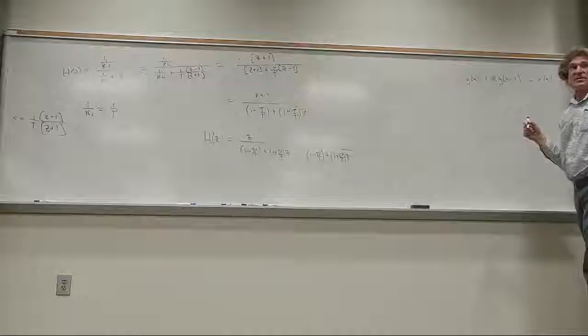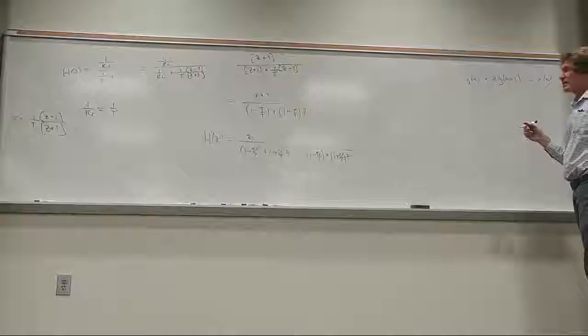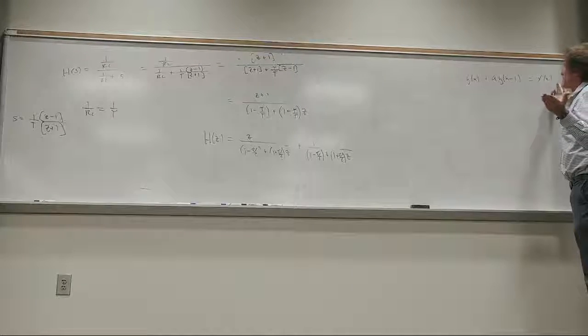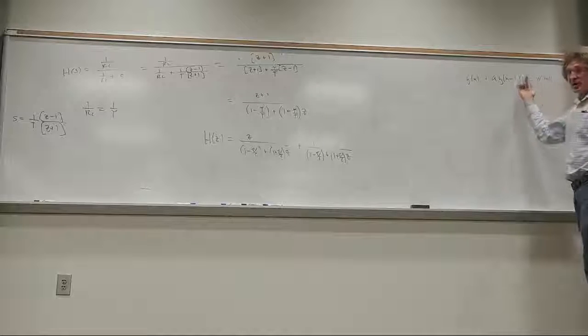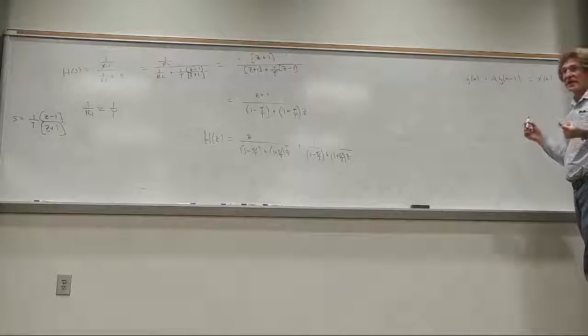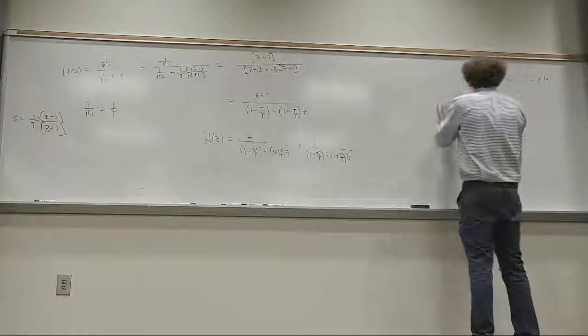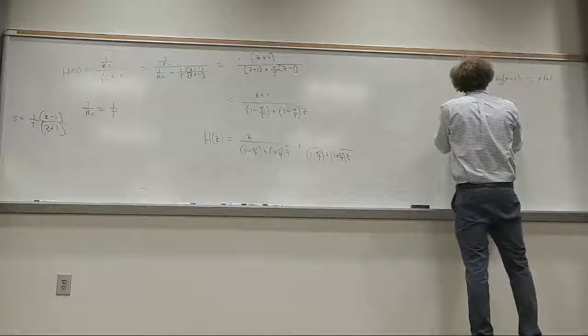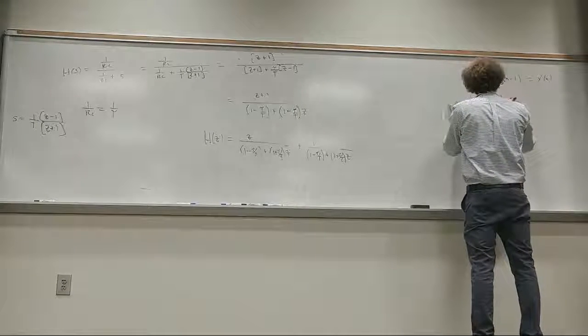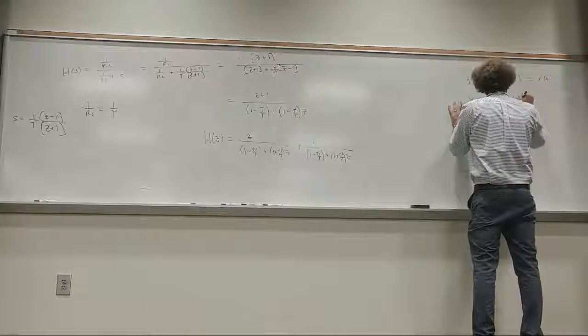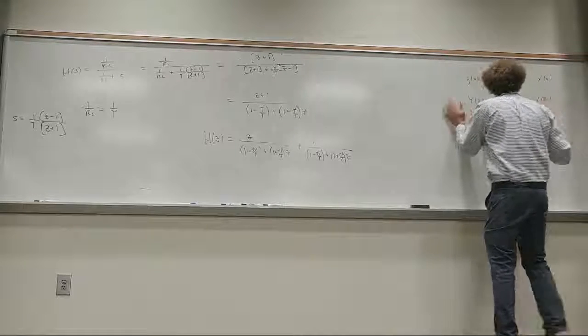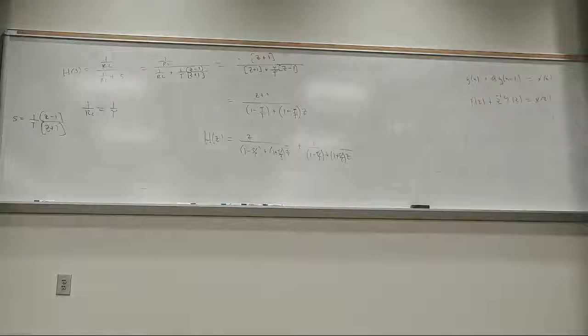Now that's a difference equation, correct, class? How did I get it? I mean, I created it. What is the z transform of this? First, what is the H of z of this? Well, this would be Y of z plus z to the minus 1 times Y of z, correct? Is equal to X of z.